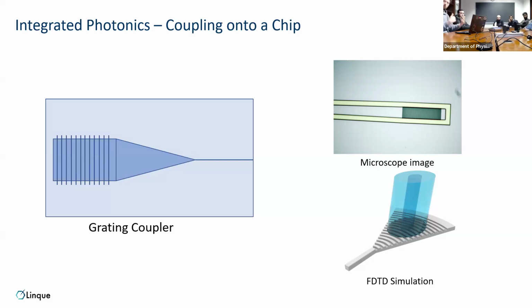Depending on how complex this is, this can work really well. If you just use one layer, then you have a transmission loss of about 5 to 6 dB, which means that you get 10-20% into the chip, which for some applications is good enough. In extreme cases it can be down to 3 or 2 or even 1 dB, which means that 70 to 80% of the light actually gets into the chip.